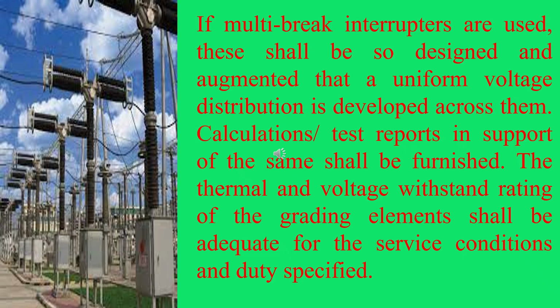If multi-break interrupters are used, these shall be so designed and augmented that a uniform voltage distribution is developed across them. Calculations and test reports in support of the same shall be furnished. The thermal and voltage withstand rating of the grading elements shall be adequate for the service conditions and duty specified.